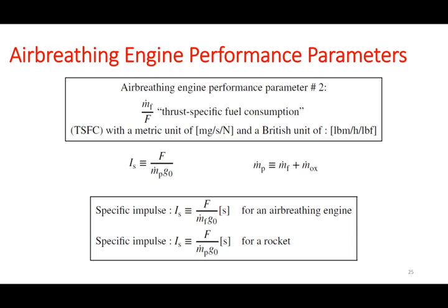This TSFC is essentially, as is obvious from its name, the amount of fuel you are going to use to be able to generate a certain amount of thrust, right? Of course, we always want to use a smaller amount of fuel to generate more thrust, so we want to minimize this. And it's a very important parameter when dealing with commercial airlines.